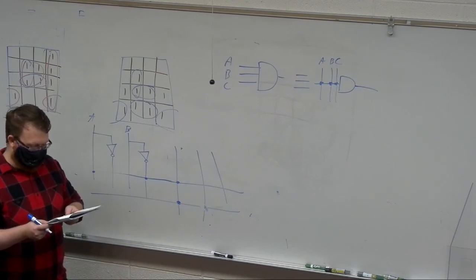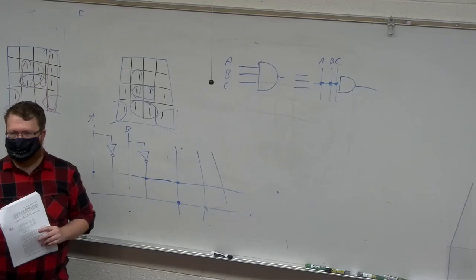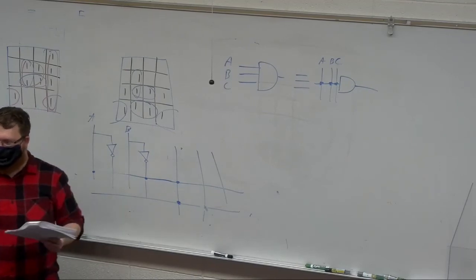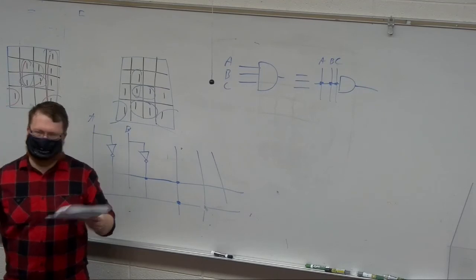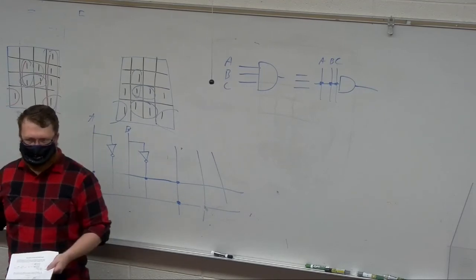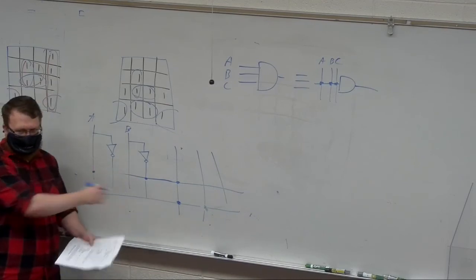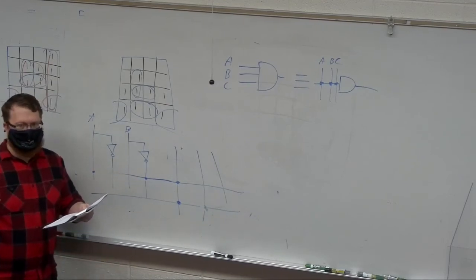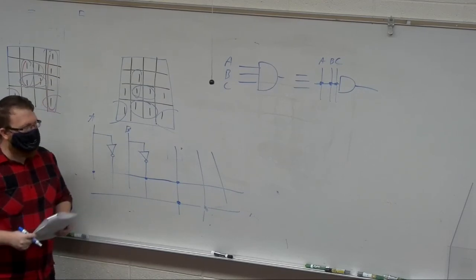I really don't want to draw the whole thing. I highly recommend going and just looking at figure 3-17. I think I've explained enough that it will make sense. It's on page 152, and it's an implementation of a full adder in PLA logic. And you can imagine that it starts getting a lot of these horizontal lines going to AND gates, and so it's got 4 ANDed terms into OR gates, and so on and so forth.